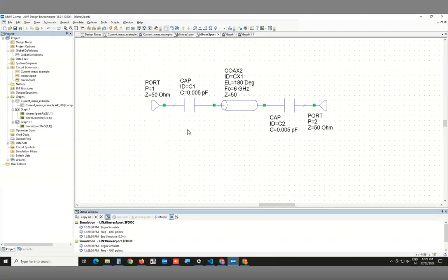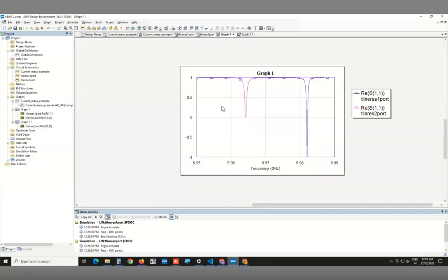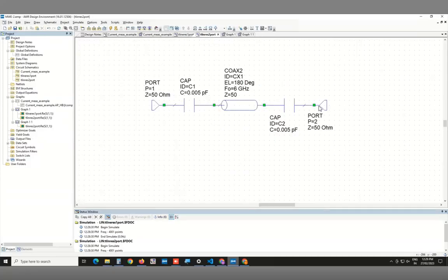Remember what we talked about just in the beginning, that when I had a single port and there was nowhere for the energy to go except come back, you will not see any response in the magnitude because all the energy is coming back in steady state. So the magnitude doesn't change, and information is there only in the real part, imaginary part of the phase. Now, that's really not true in this case, right? Because now there is this other port. Port is a place where energy can go. Remember, I said that's like two mirrors now, the energy can leak out.